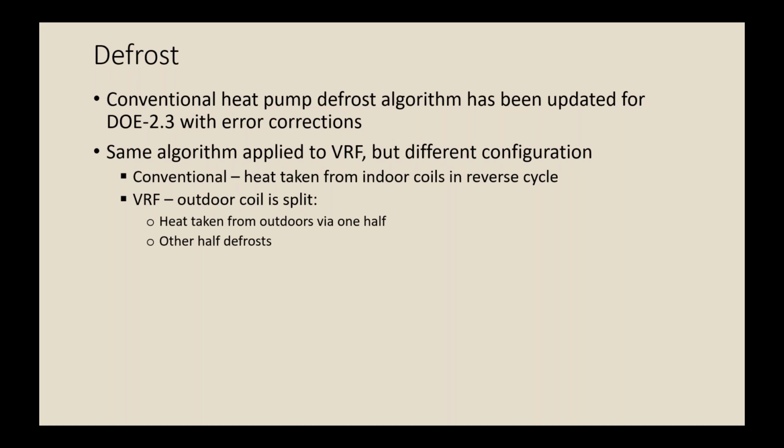And basically that algorithm has to do with how frost accumulates on a coil and how frost is melted from a coil. The VRF system uses that same kind of physics-oriented algorithm, but it has a different algorithm for how the configuration of defrost happens.